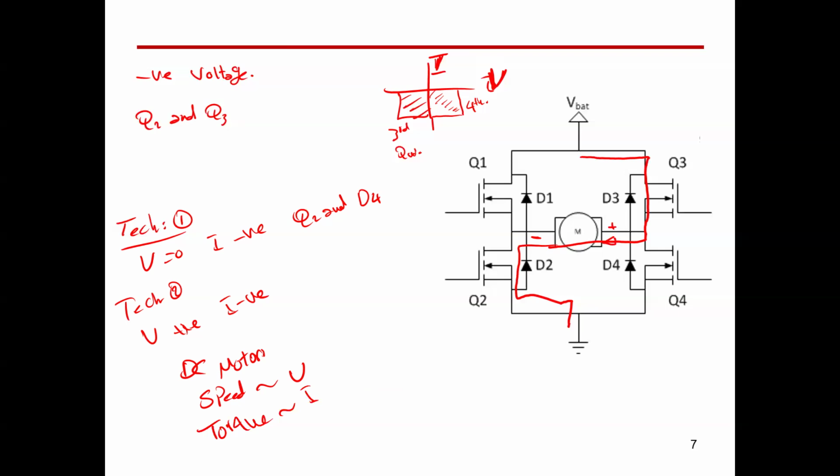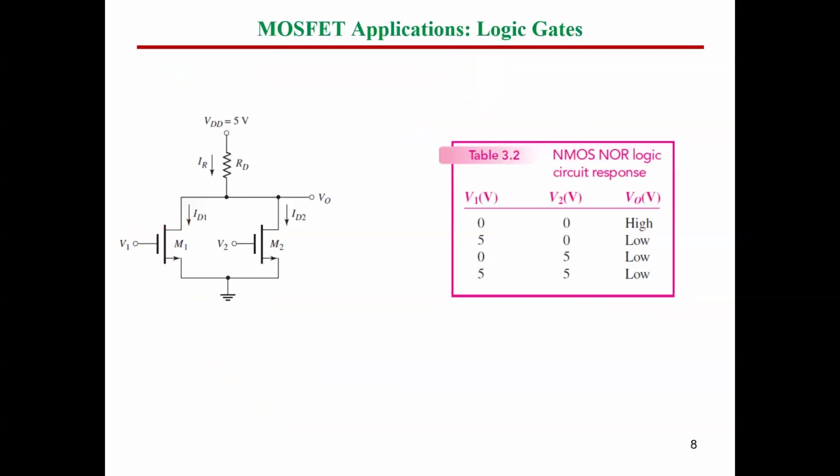In regenerative braking, the torque will be reversed, but the motor speed stays in the same direction because you cannot move the car backward. You need to continue moving in the same direction. So torque will be reversed only, but this cannot be visualized. Voltage reversal or speed reversal is visible because you will see the motor rotating in the opposite direction. So this is regarding the 4-quadrant operation.